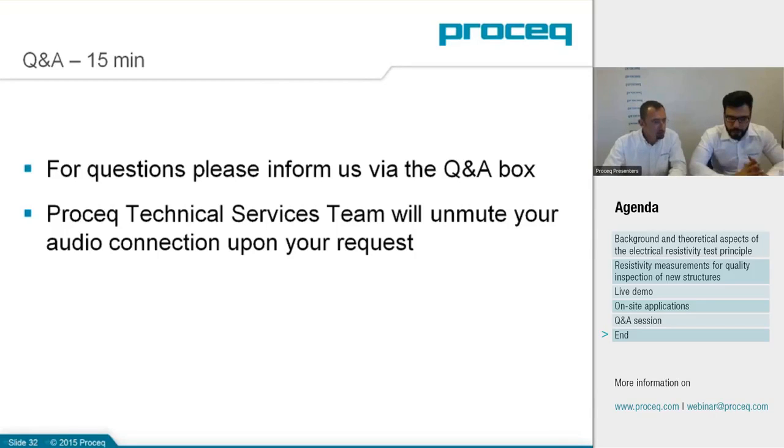Okay. What's the effect of products like fly ash, microsilica? They all increase the resistivity. The final resistivity of standard Portland cement will be lower than that of silica fume or ash concrete.